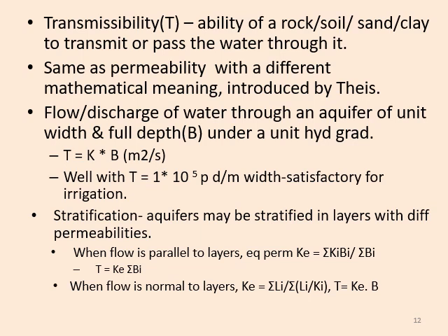We can write it in equation form as T equals K into B into 1, where B is the full depth, 1 means unit width, and K is the coefficient of permeability. So here the unit of T is meter square per second, since K is in meters per second and depth is also in meters.